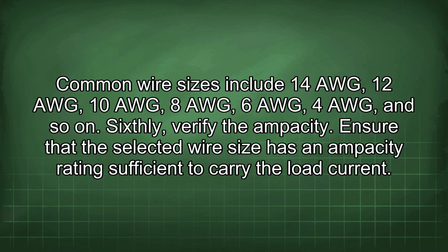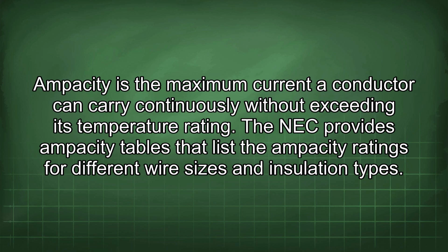Sixthly, verify the ampacity. Ensure that the selected wire size has an ampacity rating sufficient to carry the load current. Ampacity is the maximum current a conductor can carry continuously without exceeding its temperature rating. The NEC provides ampacity tables that list the ampacity ratings for different wire sizes and insulation types.